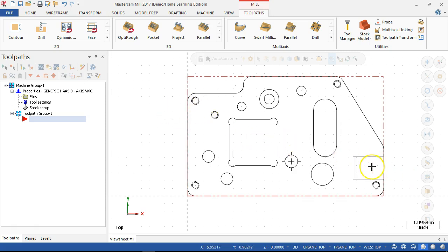Looking at the part, first question you should ask is, does this need to be a square corner? Round tools do not cut square corners. I have to set this up as a secondary operation to come in from that side. That's an additional cost. That's an additional time for quoting this part.